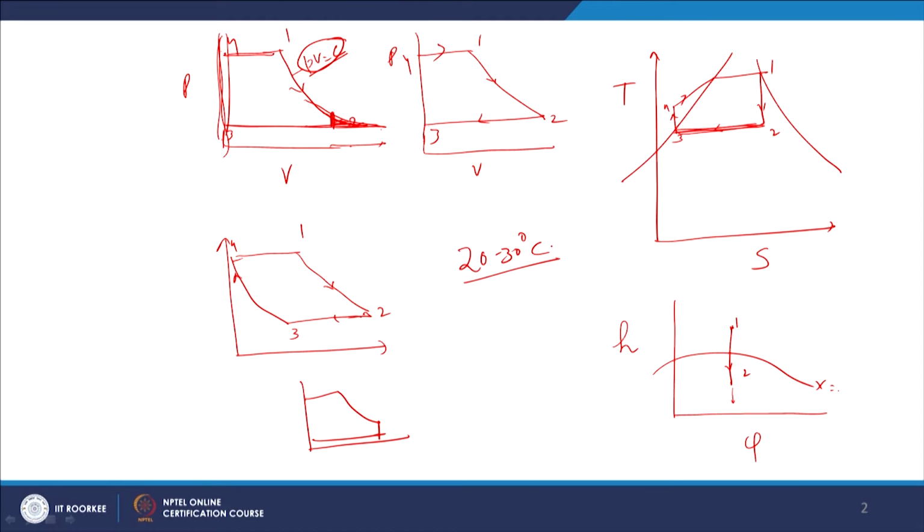So if the steam temperature is lower than this, in fact the steam will be getting heated rather than extraction of heat taking place. So the temperature of steam has to be higher than this value, at least 10 degrees centigrade higher.